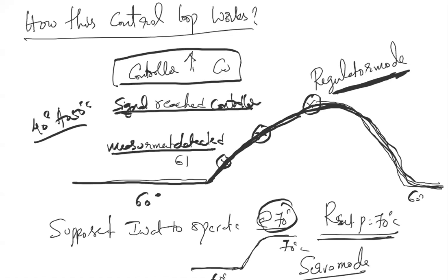So in what instances is the controller active? When everything is working in steady state, the controller is inactive. If there is a disturbance, then my parameter changes. Then the controller will come into action and set the system back to the previous steady state. That is one point where the controller comes into the picture. The second point is, now everything is working in steady state, but you have changed the set point, then also the controller will become active. That is called servo mode of the controller.